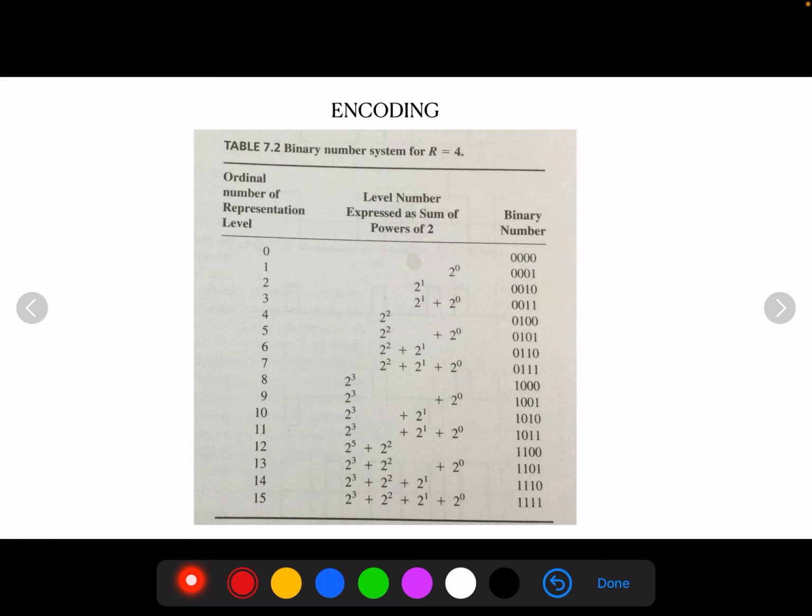To exploit the advantages of sampling and quantizing for the purpose of making the transmitted signal more robust to noise, interference and other channel degradation, we require the use of an encoding process to translate the discrete set of sample values to a more appropriate form of signal.